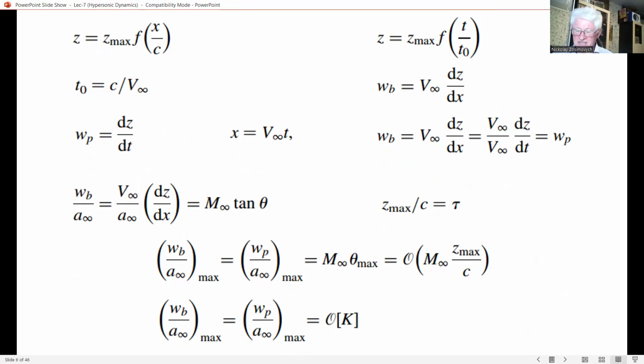So this last equation on the bottom indicates two points. First, the conditions for the hypersonic equivalence principle are the same as those for hypersonic similarity, which makes absolute sense, considering that the hypersonic small disturbance equations are the basis for both.